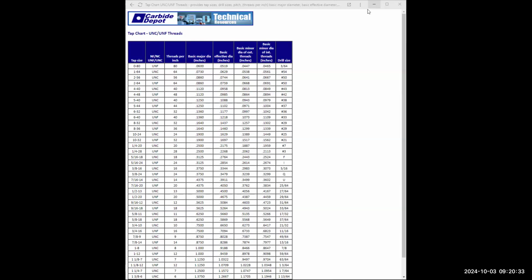I'm kind of running out of room a little bit here, so what I'm going to do, I'm going to type in leader, enter. I'm going to type in near, enter, and I'm going to do this one next. Turn off F8. Come about right there. Keep the angles roughly about the same.